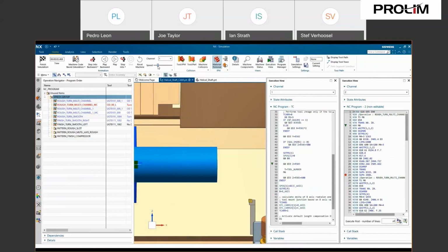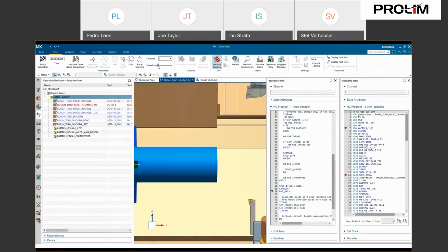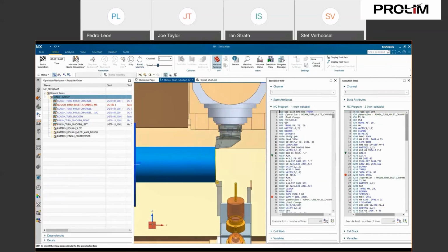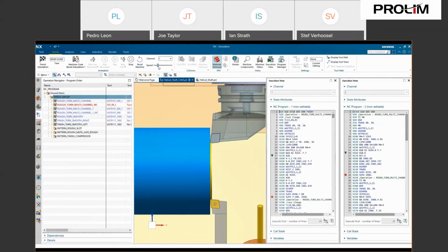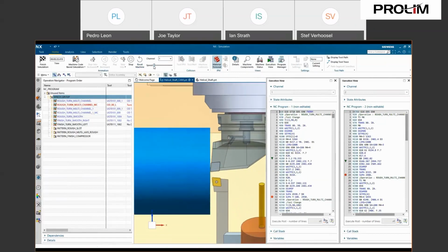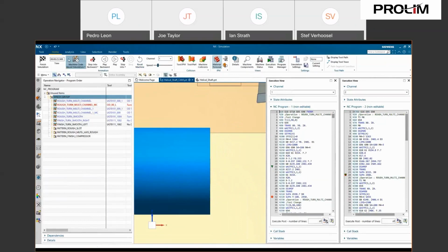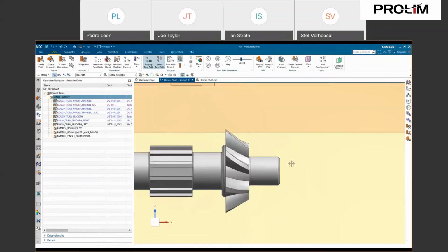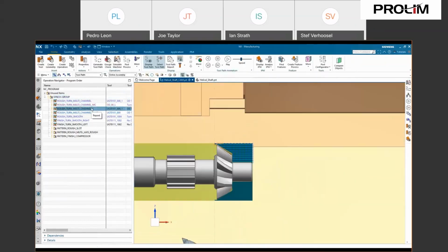As I said, this is our out-of-the-box Sim15 kit, so anybody can have a go at this with their NX setup. Okay, so there's two tools coming in, doing their merge toolpath, and as we just slow it down, you'll see the lower turret comes away and the upper turret finishes that last 10 millimeters. Okay, I think you'll find that's a useful tool.